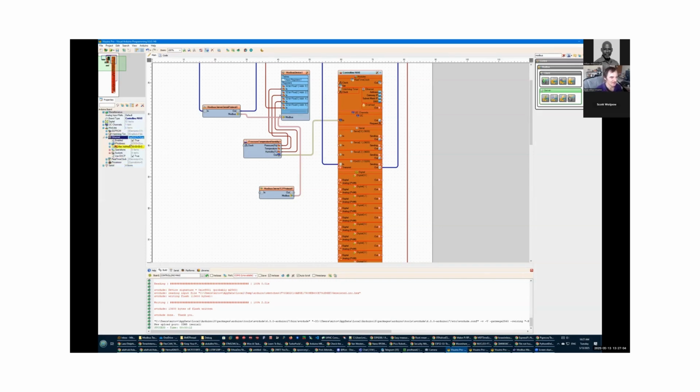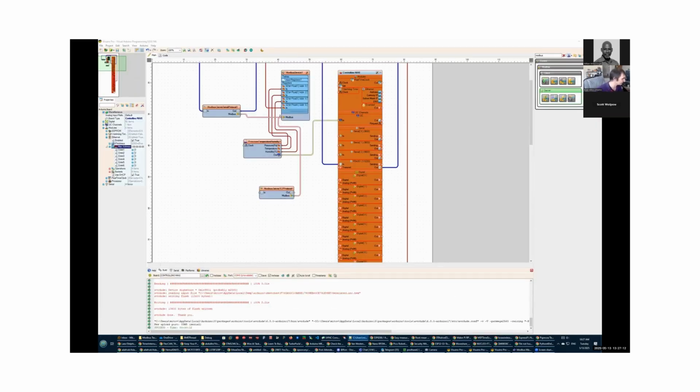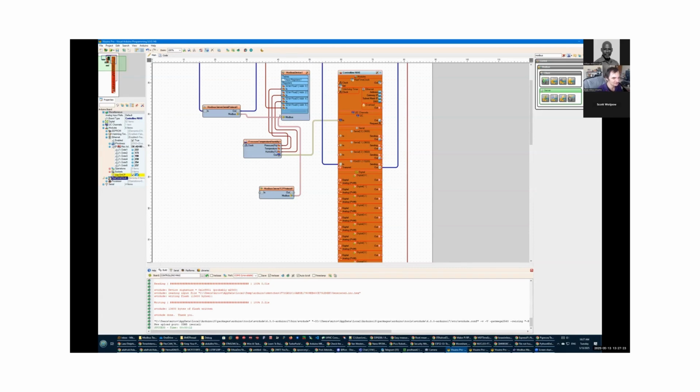And again, there are HMI softwares that control over Modbus. But what I will do is I'm going to set up the Ethernet, and I have some notes here of what I need to set for the Ethernet to work. For this specific device, it requires manual entering of the MAC address. So I have the MAC address ready. I will not use DHCP for this device. Instead, I will put in an IP address. And then I will need to add a socket, and that will be a server socket.